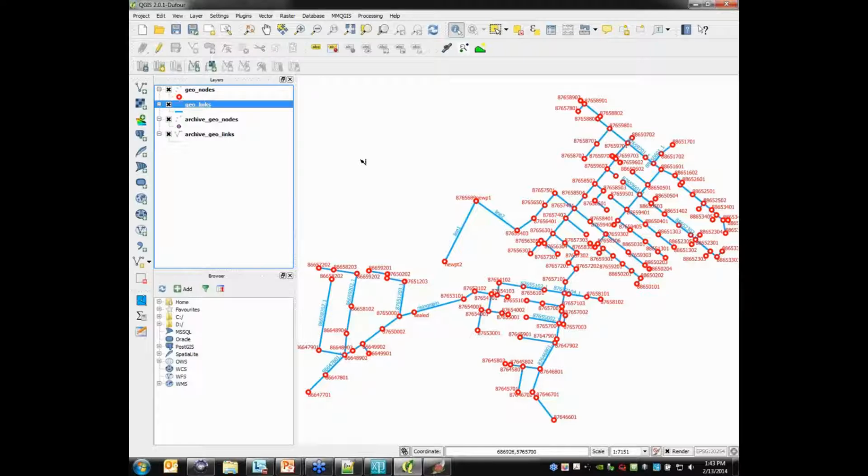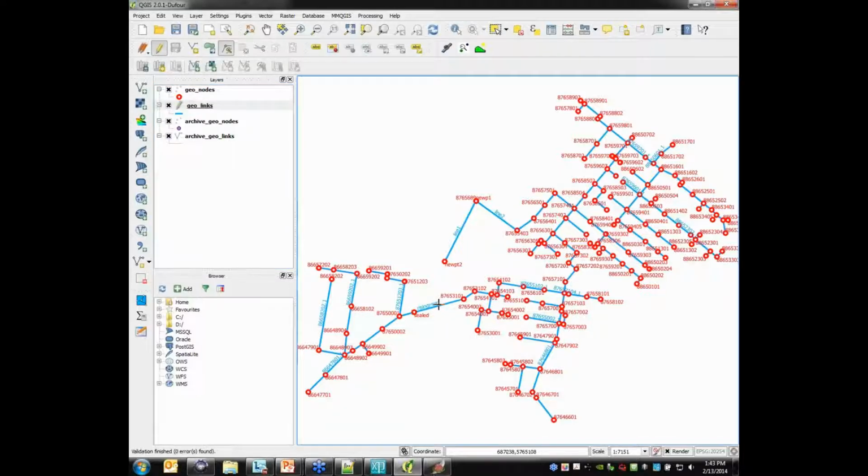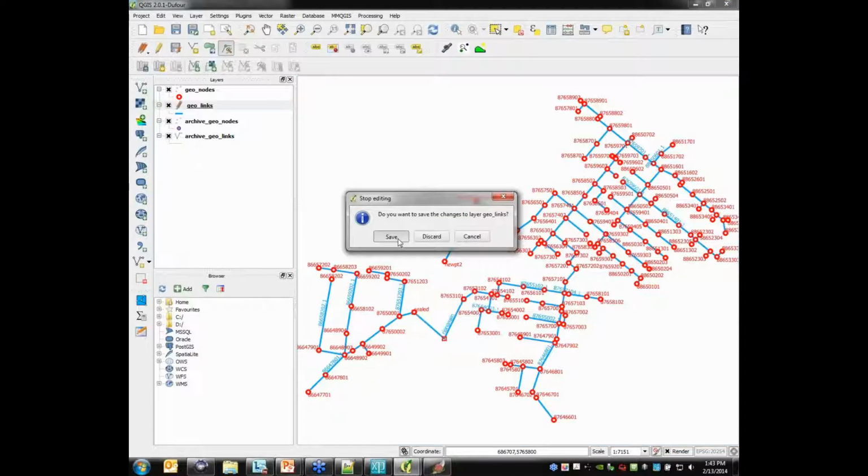The final thing that I think comes up often, especially in the world of sanitary sewer, is that perhaps I have a force main, and so I have a complex polyline that has more than two vertices. In other words, a vertex exists in between my two lines. That's something that I can handle here. So let's say this example, this rising main, actually is a force main. So let's say it looks something like that. I'll hit save, and you can see I have this little bend in there.